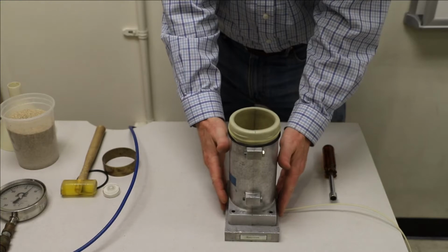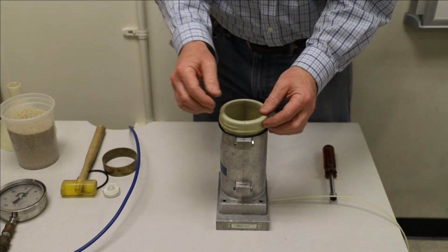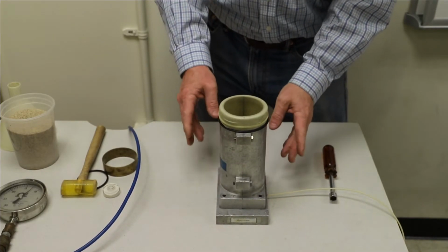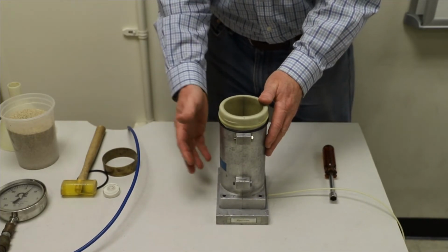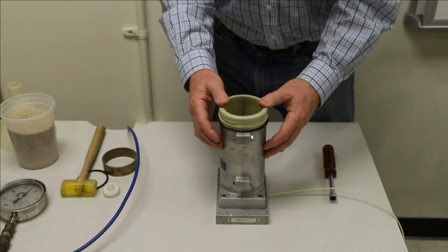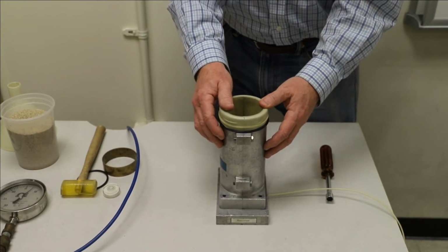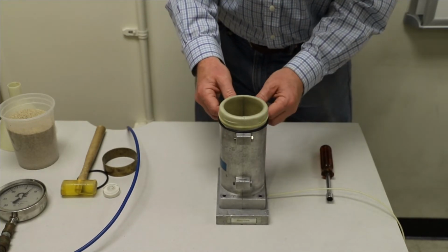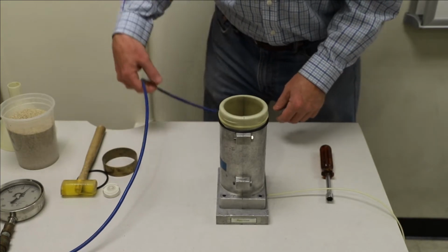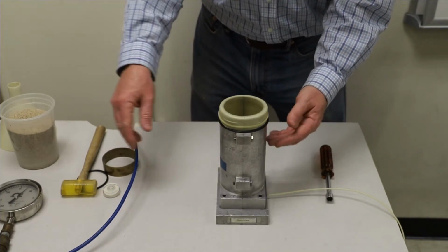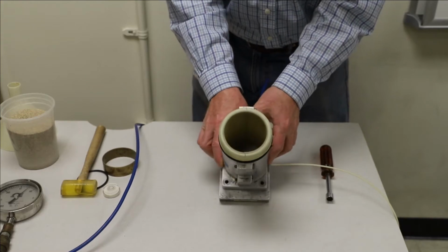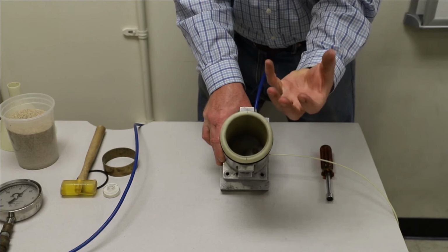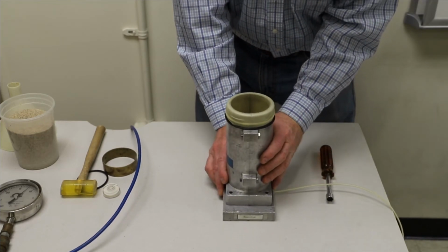So when we want to prepare the dense or high density specimen, we're going to start the same way. We have the same equipment. The mold is placed around the membrane, around the bottom cap. The membrane is sealed to the bottom cap. We've tightened up the bolts, so we think we have a nice seal. The blue vacuum line to the mold is reattached to the vacuum supply, and you can see we have a nice cylindrical fit there. The membrane is being pulled out tightly against the